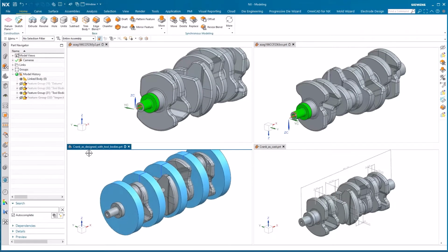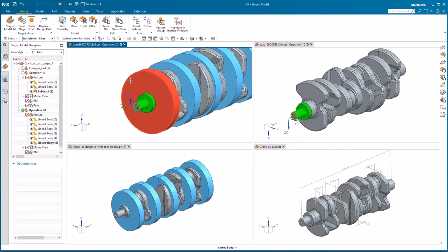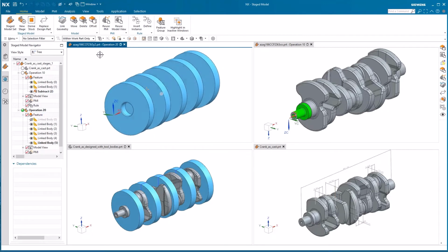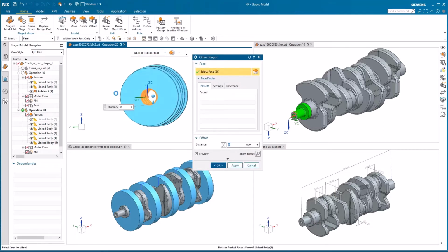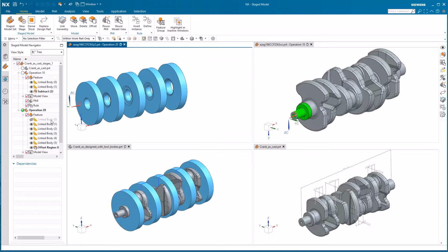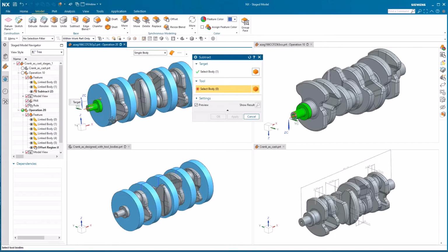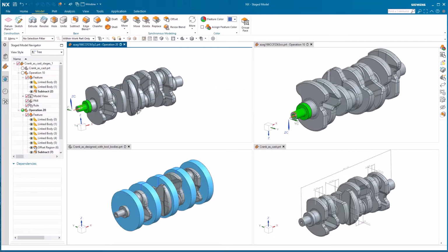And now we'll go ahead and use another tool body from our finished production part here. As we're doing this, you can see how easy it is to reuse information from multiple parts if you need to do that. In this case, we're using some tool bodies from the finished production part, sending that into a stage, and we need to add some offset here to these interior cylindrical faces. So we're going to go ahead and add a little bit of offset here, 0.35. We'll flip the direction and then select OK. Once we do that, we use a subtraction Boolean operation, pick our target body, and then pick our tool bodies here to subtract that material away and machine that material away at this stage.